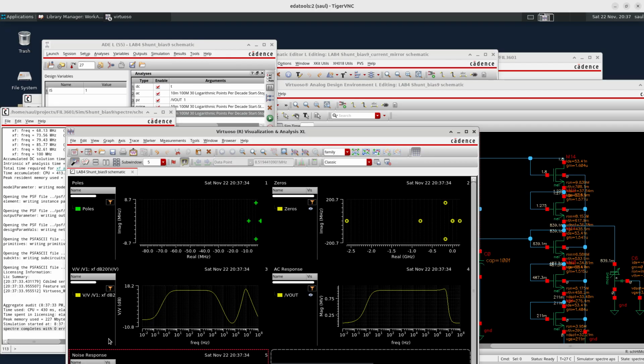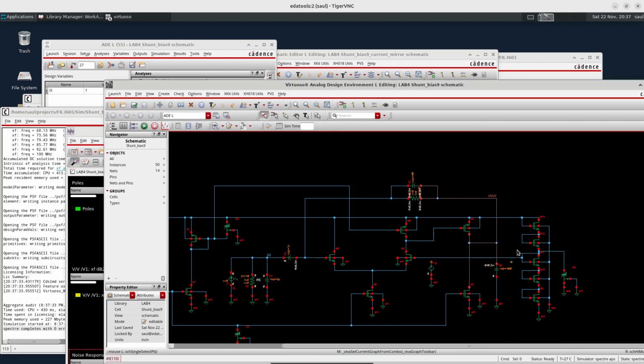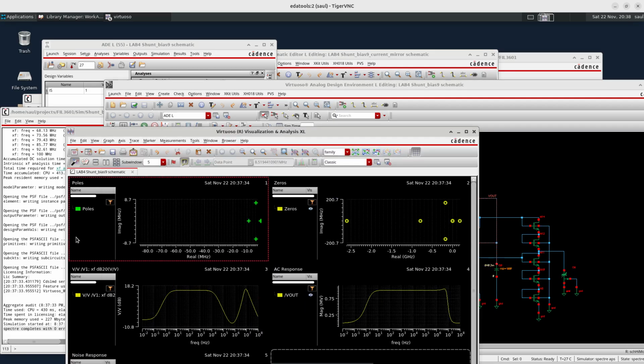And then we see that it is totally different now. So the power supply rejection ratio has changed a lot. There is very little attenuation, and we can see directly that any change in the power supply, these are diodes, so it works almost like a voltage divider. So any variation here is propagated directly to the voltage reference, and at low frequency the capacitor really doesn't work at all, so it doesn't help, and then it just deteriorates and even gets amplified at relatively low frequency. Even that variation in the power supply gets amplified.